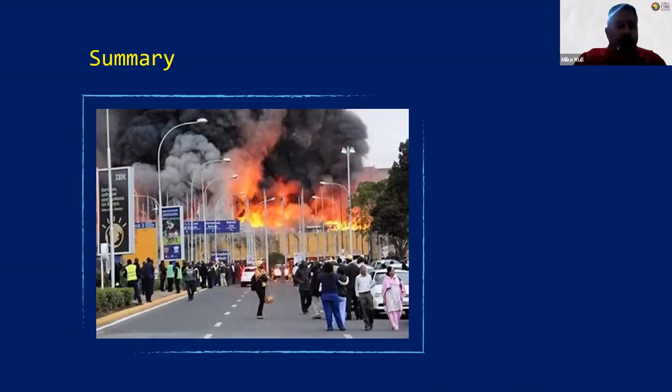How long has the fire been going? That's something we're certainly going to consider, and the impact on the structural components. It's also going to tell us whether we might still be in the growth stage, or whether we're seeing some fire activity that indicates we're back into that decay stage.